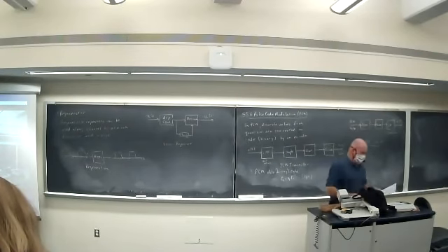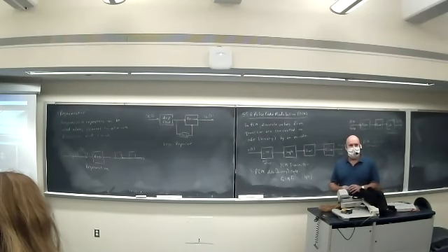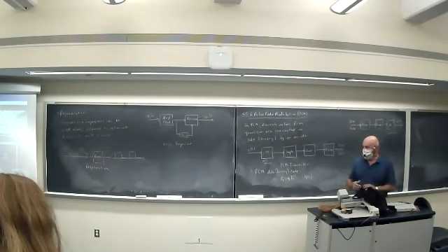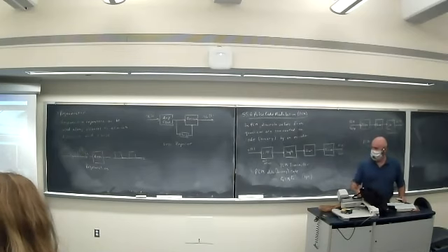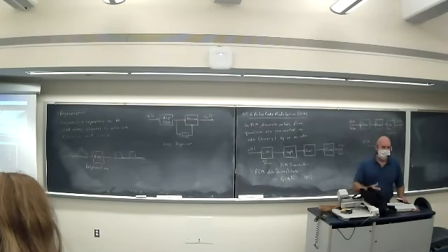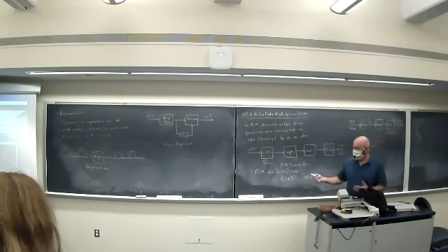But regeneration gives digital communication systems a huge advantage over analog communication systems, which can't remove the noise or unknown types of distortion. With a regenerator, I can completely regenerate a brand new digital waveform, though errors can occur.